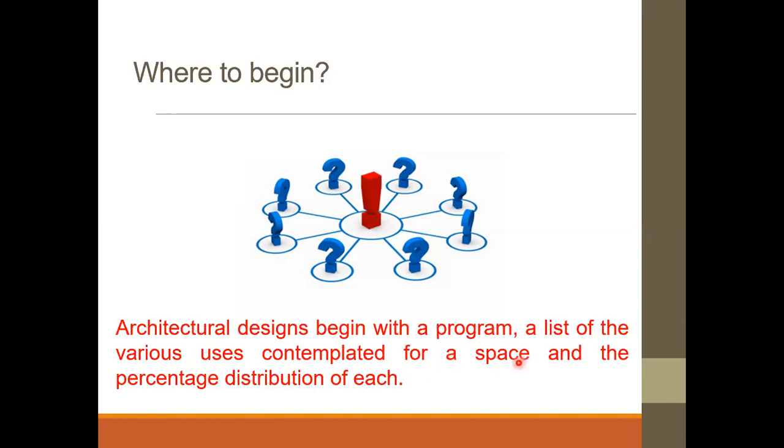The first is which types of spaces are going to be placed in that particular building, and then we distribute the square feet areas roughly as per standards, guidelines, and existing examples. For example, in commercial apartments, we sometimes define that the area of a bedroom should not be greater than 150 square feet, or it should lie between 130 and 150 as per standards, or the height of the door should not be less than 7 feet.